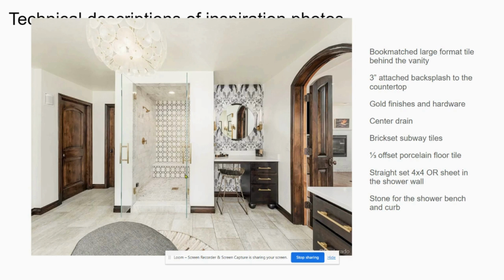They have stone slabs, the same countertop here on the shower curb and the shower bench. When you are putting in a shower bench and a curb, you can't have a grout line going through those. It's like a hazard. People would fall or things would fall over. So you have to get solid stone. You can't get tiles like this for the top of your bench and the shower curbs. When you order this countertop from your vendor, you need to ask them to also cut to size these pieces, and then you will give those pieces to your shower installer.